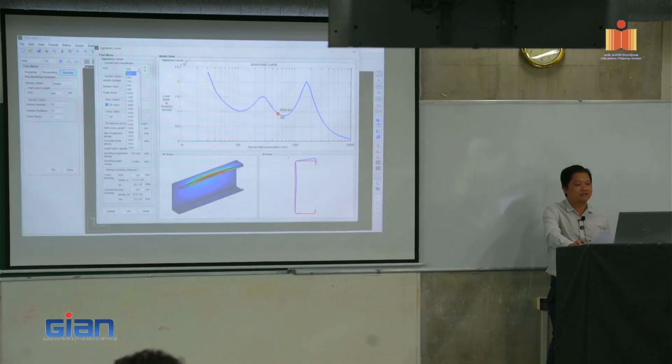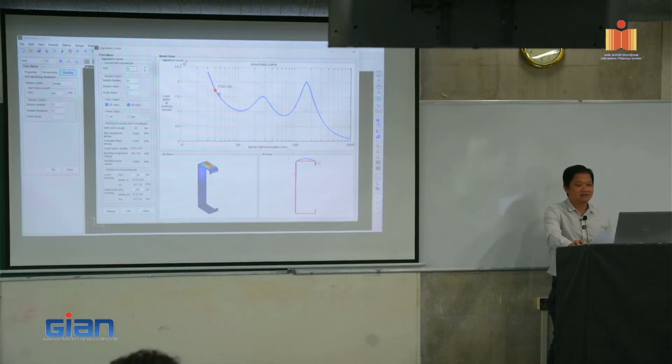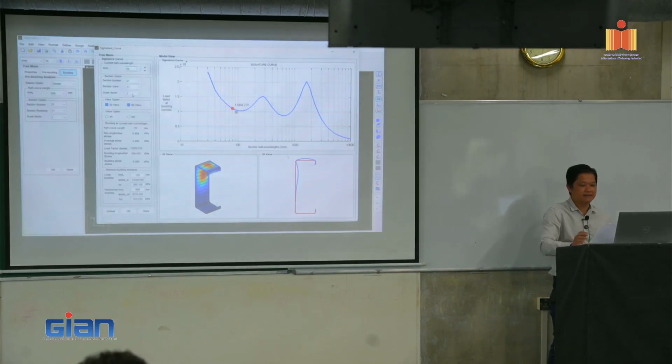You can actually start from a small one, 40. It's really local buckling. See, the junction line here is straight. It just buckles in the flange or a little bit in the web here. That's local buckling. And it's going down to 7. You see that? You can change here. And then gradually you go to 80, 90.